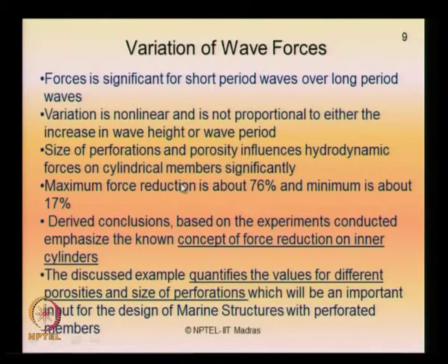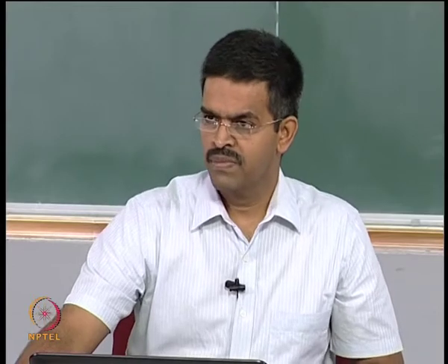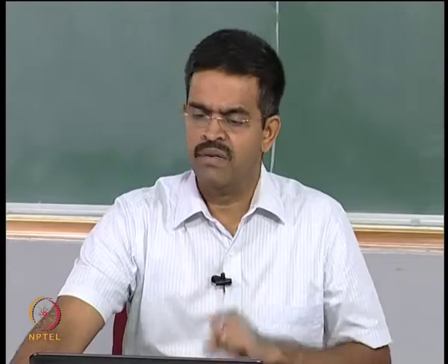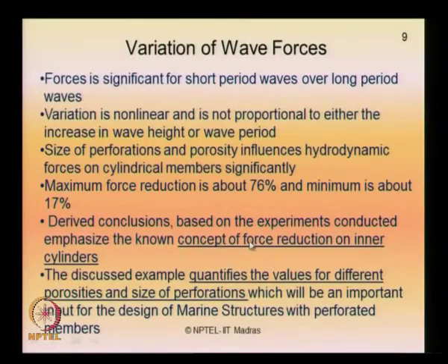The maximum force reduction is as high as 76% and as low as 17%. Therefore, one can make a very brief conclusion from this experimental study that the concept of force reduction on the inner cylinder is emphasized. Further, the discussed example quantifies the value for different porosities and sizes of perforation, which can be understood as an important input for the design of marine structures with perforated members.